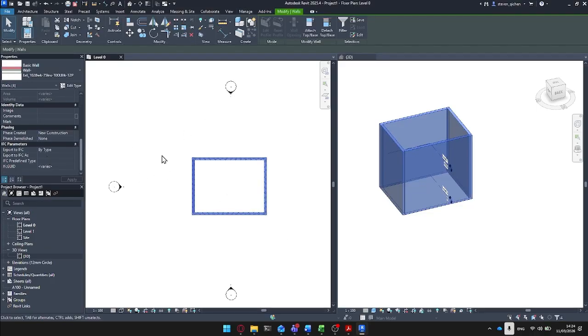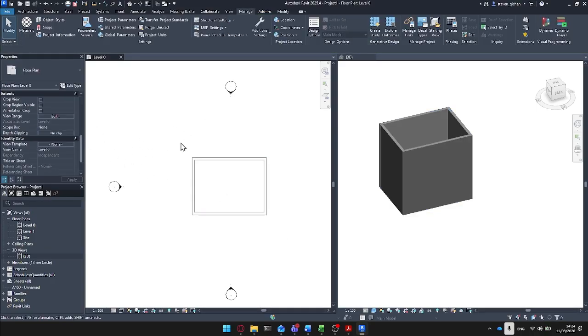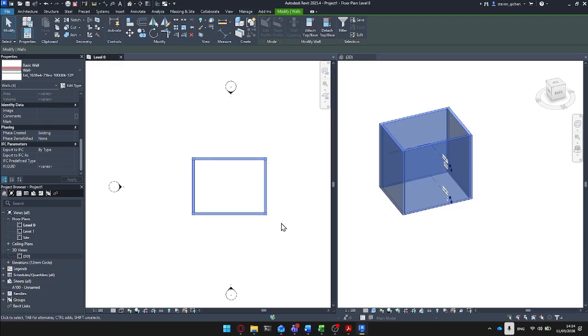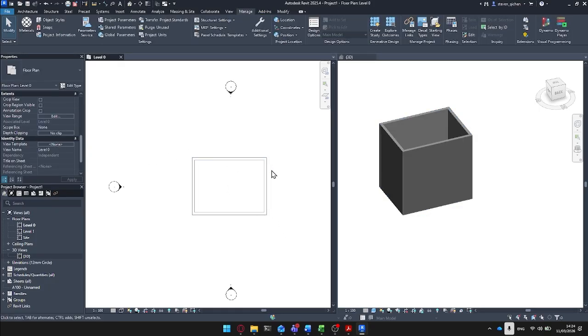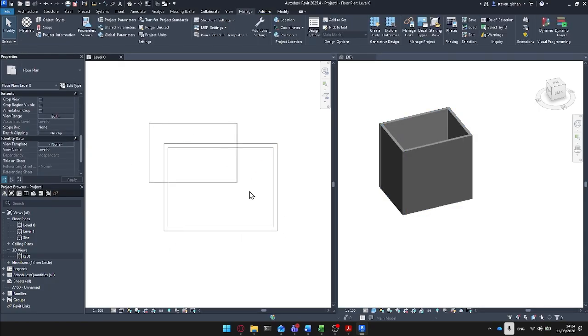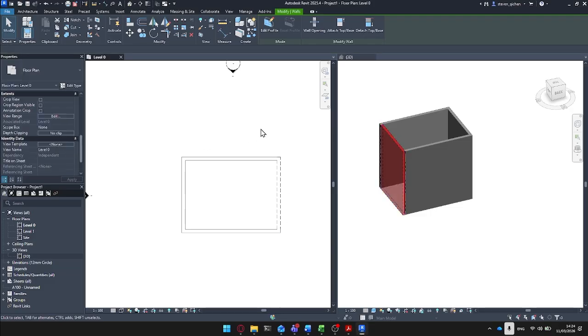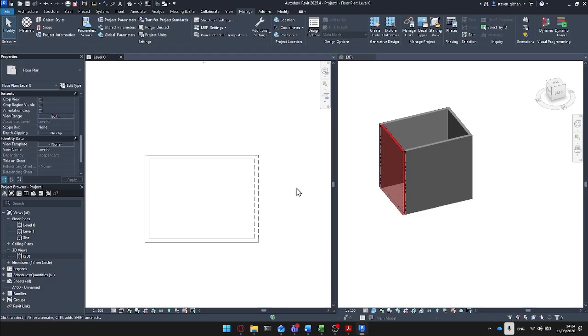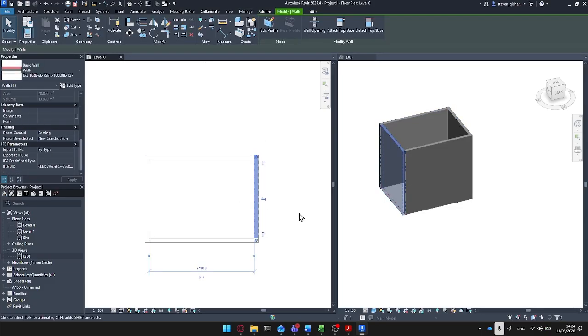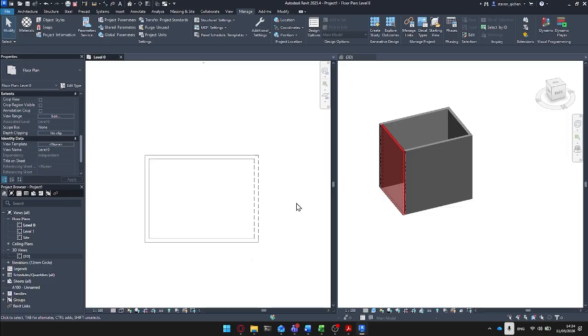So for this building we have here with the 4 walls, we're going to assign it an existing phase. And just for argument's sake, this is an existing building and we're going to demolish the wall on the right. We will write phase demolished in new construction, which tells us everything was built, but we're getting rid of it when a new proposal is implemented.